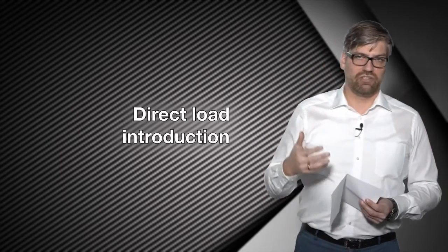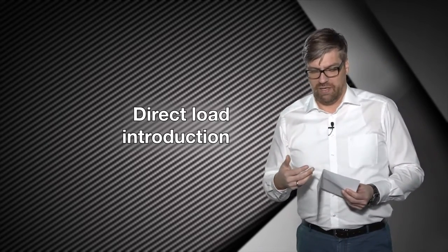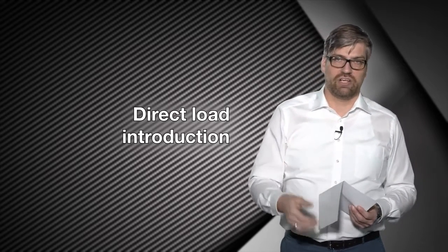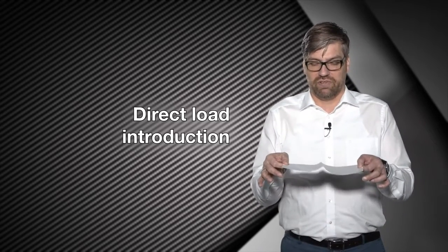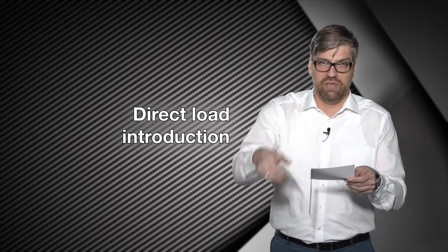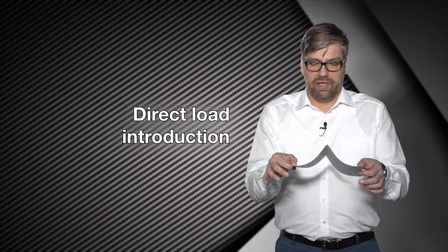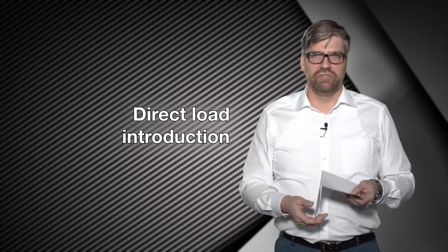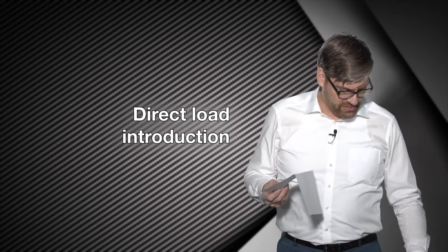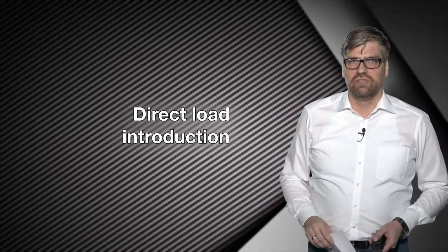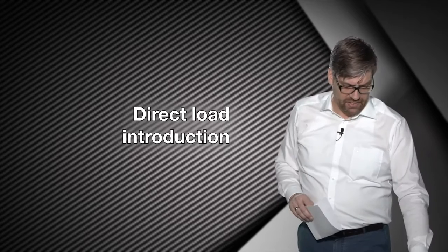That means that redirection of loads means that we have additional section forces in our structure. And these additional section forces in our structure, although we have the same external loads, reduce the load carrying capacity of my structure too. So therefore, introduce your loads directly.